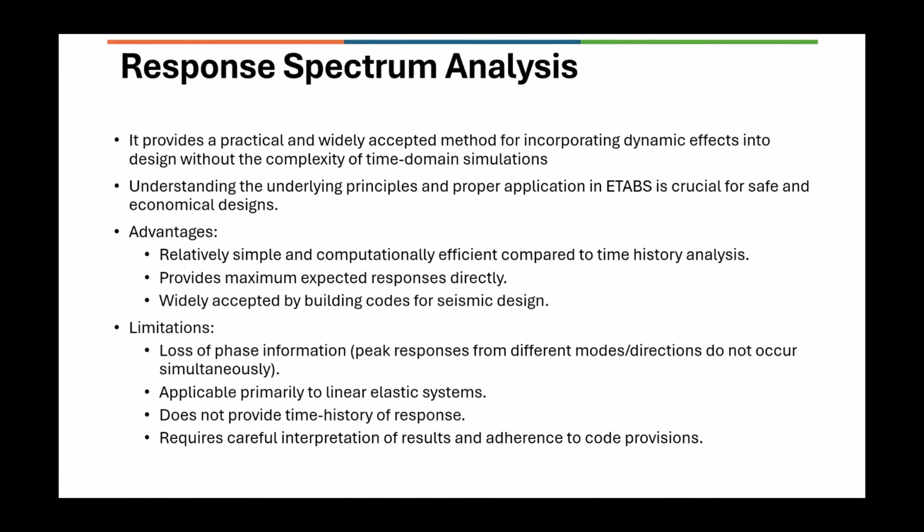It is not going to provide the time history response, which we are not interested in for the design requirement. It requires careful interpretation of results and adherence to code provisions. The code is also guiding us on how to handle the results. So that is a general response spectrum background.